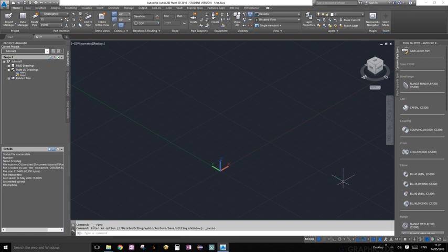For our system, a couple of things we're always going to have on: we're going to be in model space, so just leave that alone. If you click it again, it will go to paper space and vice versa. Here, we're going to have our display grid on. As you can see, this little, usually glowing blue means on. If you turn that off, it disappears.